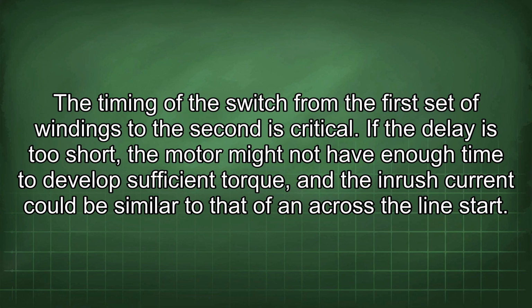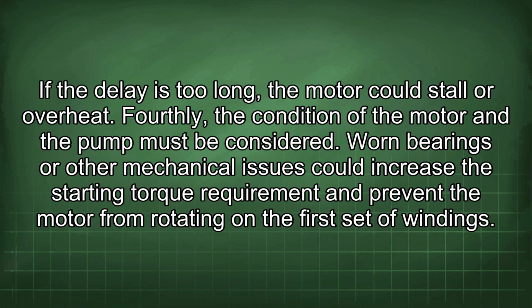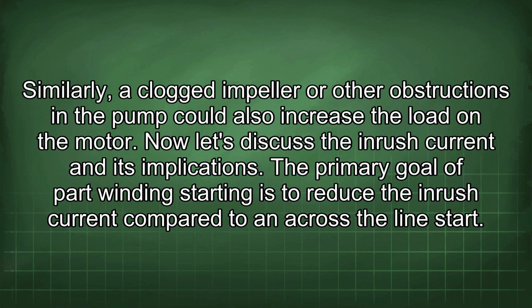If the delay is too short, the motor might not have enough time to develop sufficient torque, and the inrush current could be similar to that of an across-the-line start. If the delay is too long, the motor could stall or overheat. Fourthly, the condition of the motor and the pump must be considered. Worn bearings or other mechanical issues could increase the starting torque requirement and prevent the motor from rotating on the first set of windings. Similarly, a clogged impeller or other obstructions in the pump could also increase the load on the motor. Now let's discuss the inrush current and its implications.